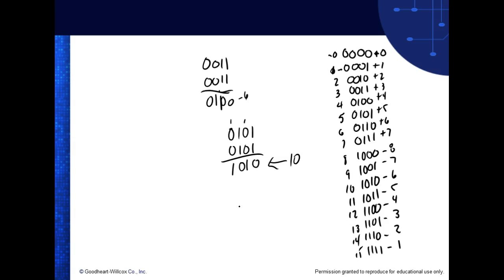If my carry bit sets, it means I exceeded the range of the numbers. So if I'm dealing with unsigned numbers, I'm going to be concerned with the what? With the carry flag. So if I come over here, what would cause a carry? Let's say I'm going to add 8. We'll just add 8 plus 8.